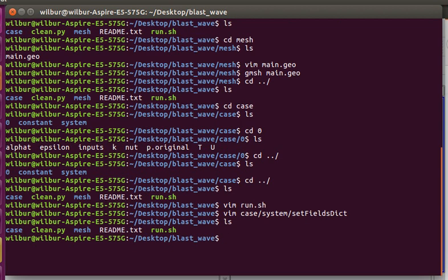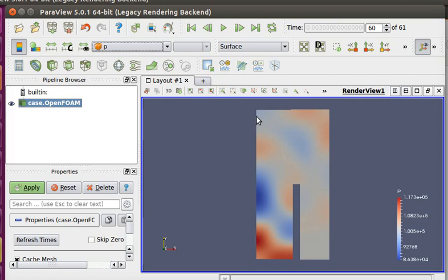So that's pretty much it. You can just run the run script. For sonicFoam, they don't really have dynamic runtime control. You have to set a fixed time step according to the stability and maybe time accuracy you want. So it takes a little longer than the other tutorials we've run, but I've run it beforehand so you can see the results.